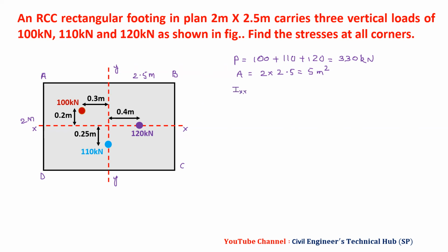So for Ixx, we have 2.5 into 2 cube by 12, and that is equal to 1.67 meter to the power 4. And then we have Iyy, 2 into 2.5 cube by 12, and we have this value, 2.6 meter to the power 4.